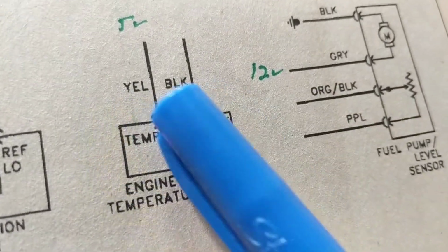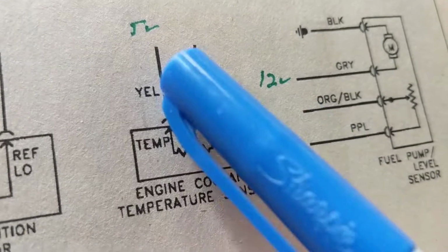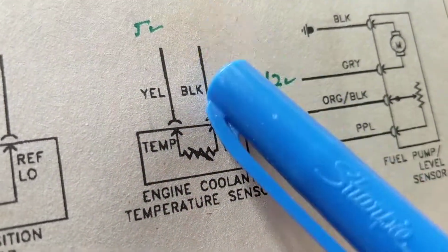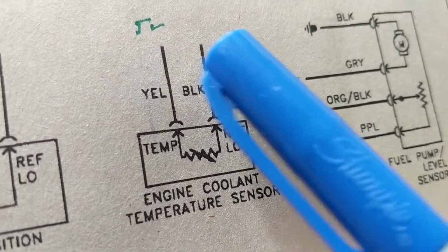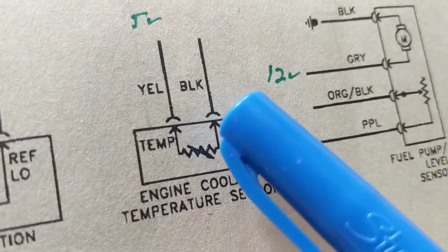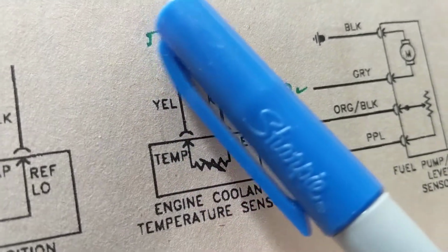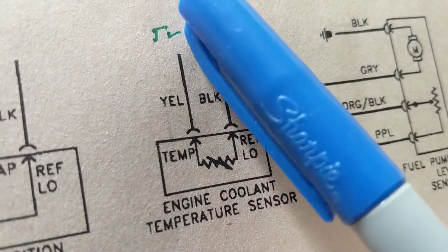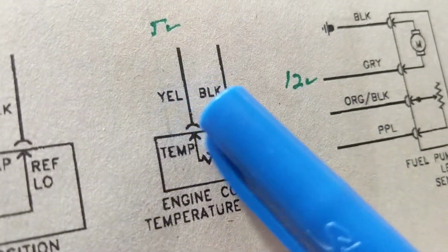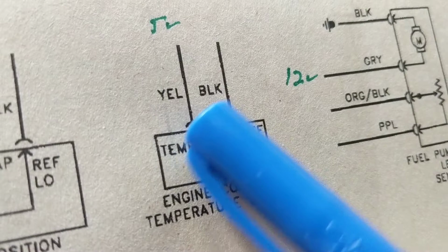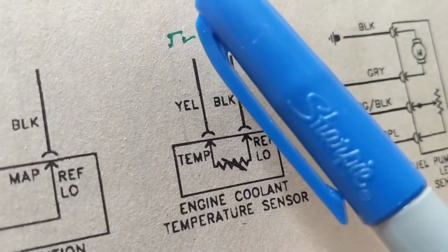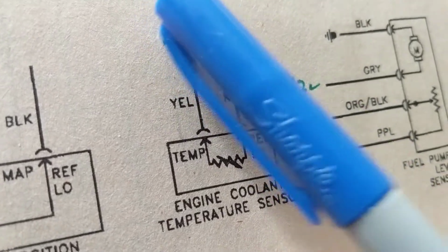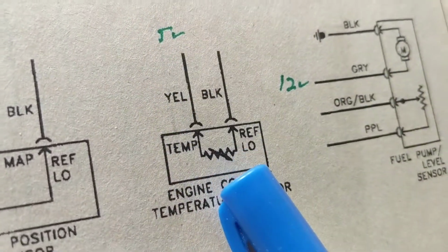How about this one? Two wires, yellow and black. How much can the computer give? The computer will give you 5 volts. And there's a low over here. So it'll give you the 5 volts because it needs 5 volts, but it will also be based on that reference. It's going to give feedback on how much this voltage goes down. So this voltage can go down to 3 volts, 2 volts, 1 volt, whatever. It cannot go past 6 volts, 8 volts, 9 volts. Why? This is the reference. It can't go more than the supply that the computer is giving it.